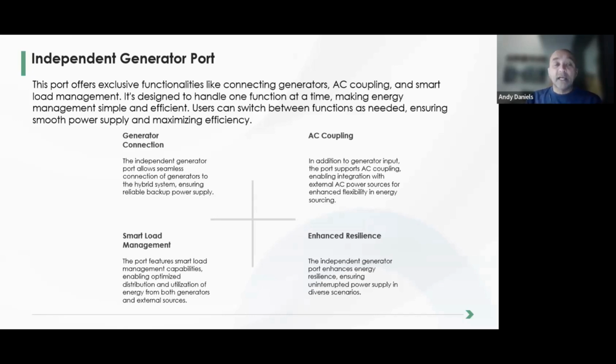You can also assign it as an AC coupling port, meaning you can retrofit your LXP to an existing grid-tied solution. You can take a feed from your existing grid-tied inverter and plug it into the gen port, and in the settings you will just assign it as an AC coupling.